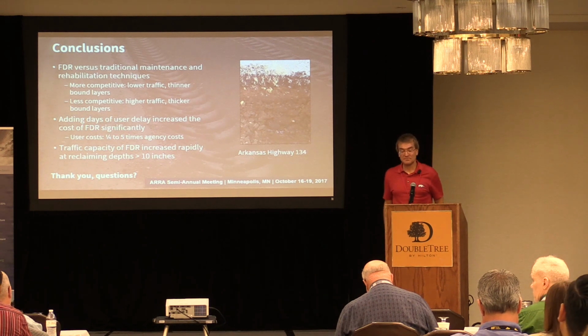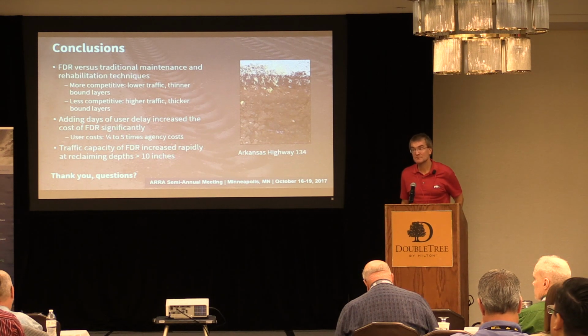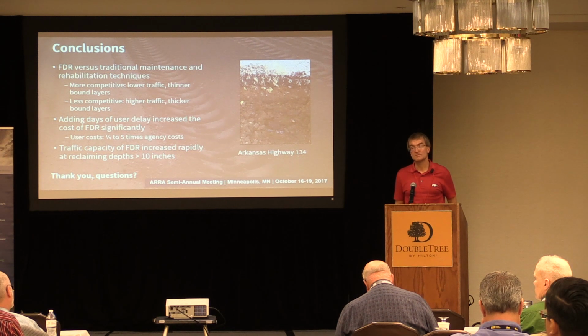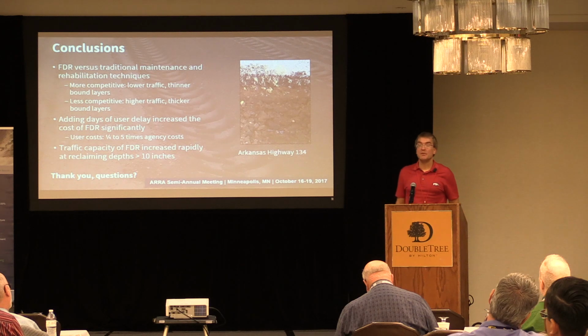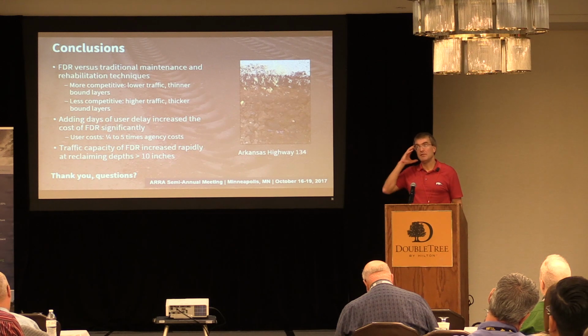Could you, just intuitively, I'm trying to figure the mill and fill with two lasting 11 years, remove and replace only 11 years, like the same. Is that because you end up with less asphalt structure, or what's intuitively the reason they're the same? Right, so the question was, why did we assume an 11-year performance period for both 2-inch overlays and mill and fill? It's because I came at it from the mindset that the pavement deteriorates at the same rate.